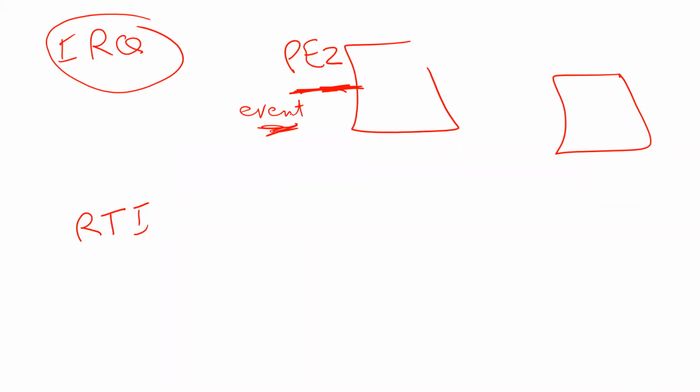When you trigger the interrupt, if the interrupt is enabled, you actually execute a subroutine. It's called the interrupt subroutine. It's guaranteed, very simple: every time there is an event, you call the subroutine.